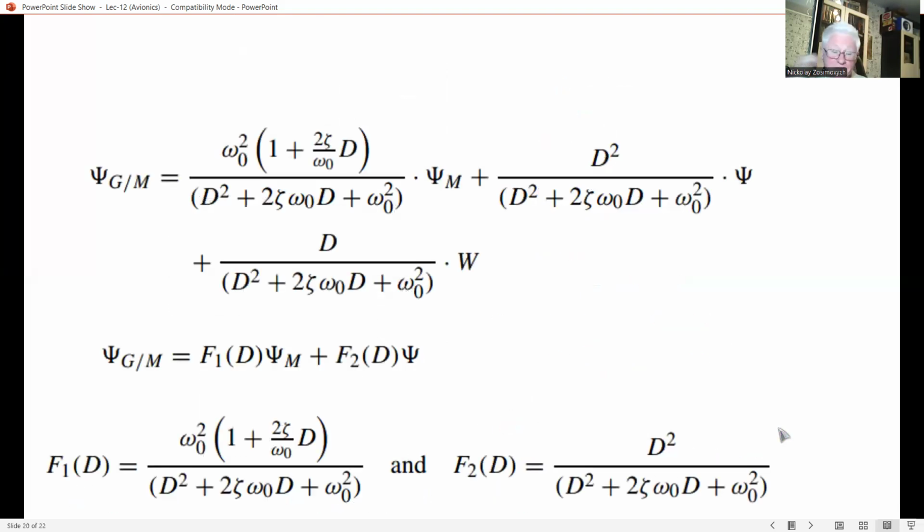And the dynamic response of the system is that of a simple second-order system with an undamped natural frequency. The undamped natural frequency is omega naught. Omega naught equals the square root of K2. And the other is the damping ratio, zeta here. It equals K1 divided by 2 times the square root of K2.